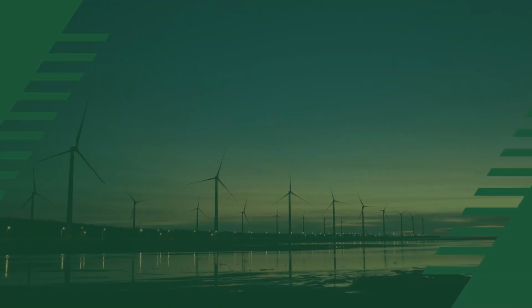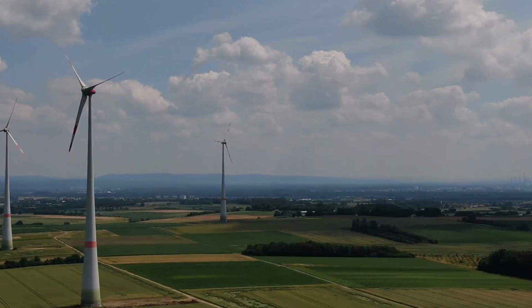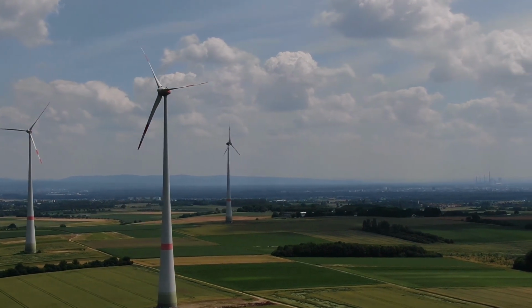Second parameter is the scale parameter and it is represented by C. The scale parameter of Weibull distribution represents the wind speed at which the probability density function reaches its maximum value. It provides an indication of the typical wind speed at the site.